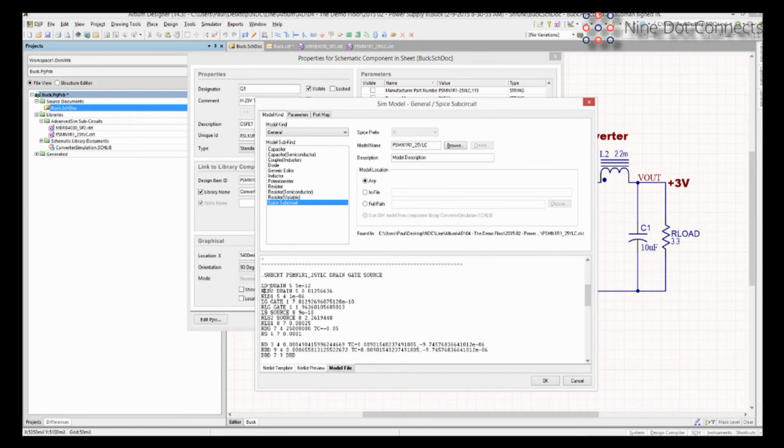For the example that you see over here, the first thing you see is an LD. This line of code represents an inductor. The prefix L, the very first character on that line, says this is an inductor. Anything after that is really just to provide more detail as to which particular inductor you're talking about. So they call this one LD.